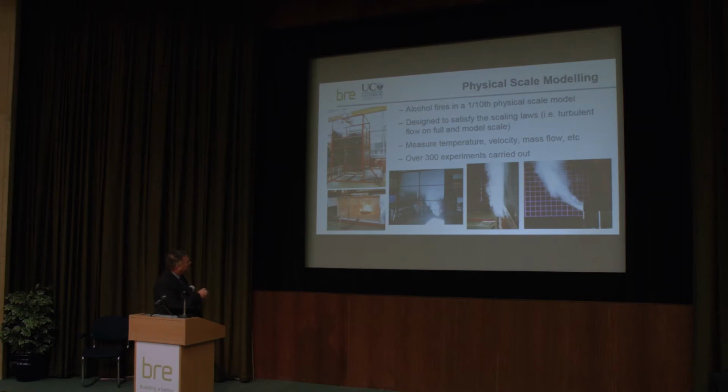And what we do is we inject theatrical smoke into the hot gas layer to visualize the plume and the layer itself. There's our compartment. We have a collecting hood here to collect the spill plume and measure the mass, and then we've got an extract duct with a mechanical fan here, so we can raise and lower the layer and look at different heights of rise, and different widths of opening as well, from wide shop units to doorway openings.